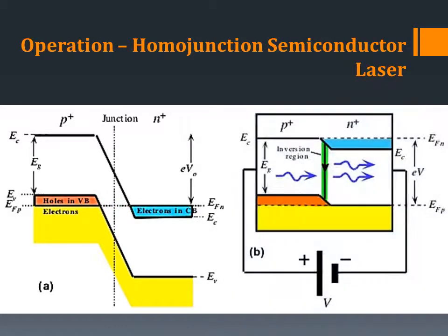Now, on application of a forward bias, the direct conduction takes place. This occurs due to high current density and the presence of an active region near the depletion region. Therefore, due to the presence of the active region, which is shown in green, the electrons which are present in the conduction band of the N type start moving towards the active region.